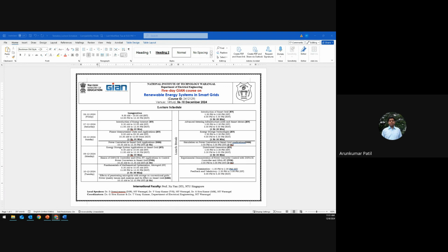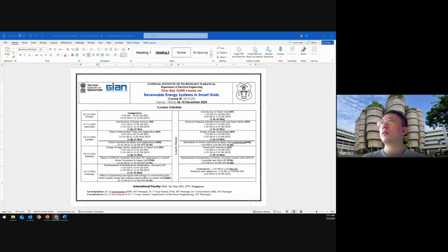Is there any other system, sir, other than OPAL-RT and RTDS, for use? For offline simulation, actually we use the PSS/E. Then we set a very small timestep, 0.01 second, for simulation. That is also possible, and you can also use PowerFactory. You can also use PSCAD for electromagnetic simulation. So they can also support very high resolution transient simulations. PSCAD is also useful.